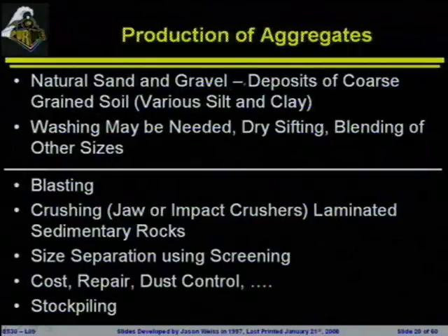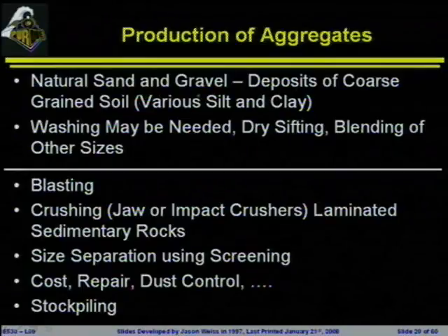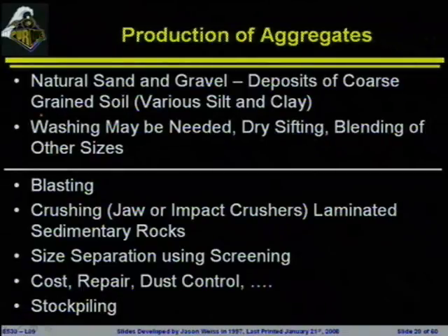Now, natural sands, pretty much what you're looking at here is deposits of coarse or fine aggregates. They're typically only going to be sieved or cleaned, and they're ready to be used. You may hear people talk about washing these. They'll be putting them through something like a cyclone to spin out organic particles, or to use centrifugal force to get rid of other things. You may see them blending these or dry sifting them, but in general, producing natural aggregates really isn't that difficult.